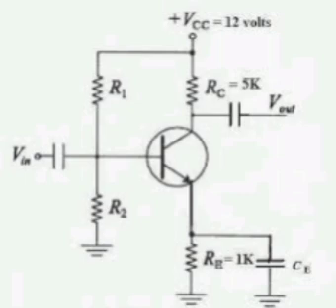The question is: calculate the flat band voltage VFB and the threshold voltage VTP, assuming epsilon ox equal to 3.43 into 10 power minus 13 farad per centimeter, thermal voltage Vt equal to 0.026 volts, Ni equal to 10 power 10 per centimeter cube, chi s, that means electron affinity of silicon, equal to 4.05 electron volts, and epsilon Si equal to 10 power minus 12 farad per centimeter.